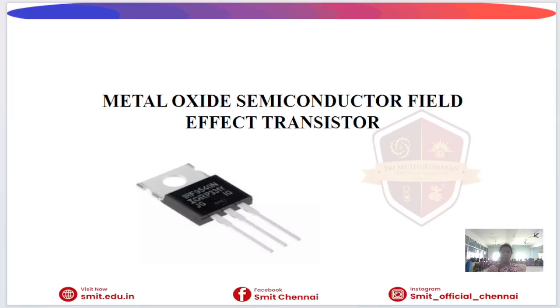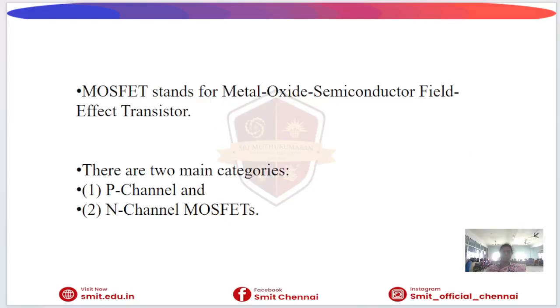At the end of the session, the student should be able to know what a MOSFET is, its construction and working principle, identify the terminals, understand the characteristics, and the applications also. So, first, what is a MOSFET? The MOSFET stands for metal oxide semiconductor field effect transistor. It is a semiconductor device used for amplification and switching.